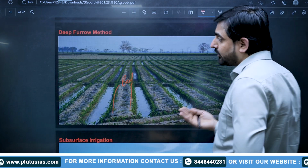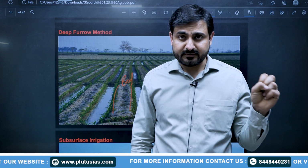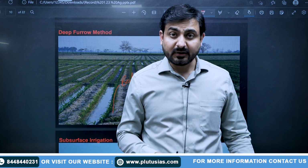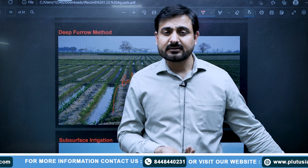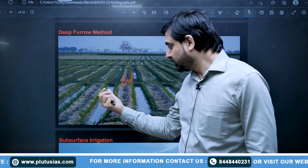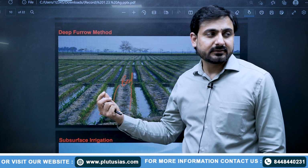Now, what are the problems with this deep furrow irrigation method? There are various problems. It requires more effort and more labor for creating the various ridges and furrows. During heavy rainfall, these furrows direct water, so water may run off from your field, and generally no crop grows inside the furrows, which hampers the overall yield of the field.